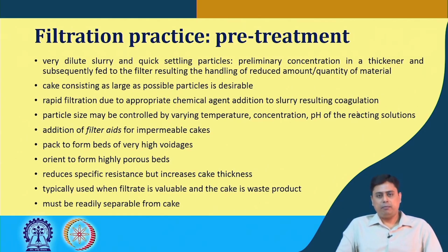Also, if this is happening by precipitation reactions, the particle size can also be controlled by temperature, concentration, and the pH of the solutions. There are also examples or practice of adding filter aids when the cake becomes impermeable, which means hard to flow inside the cake. Such characteristics of the cake are not desirable. It has to be porous in nature, so that the filtration can happen.